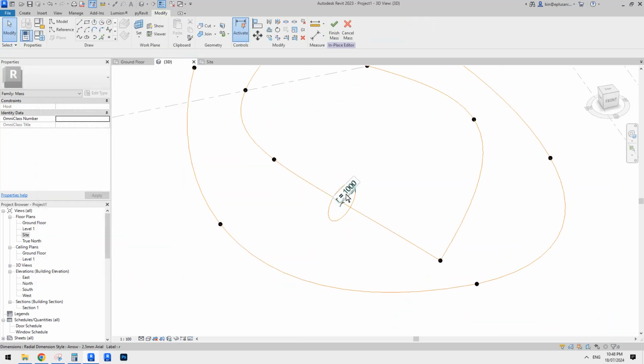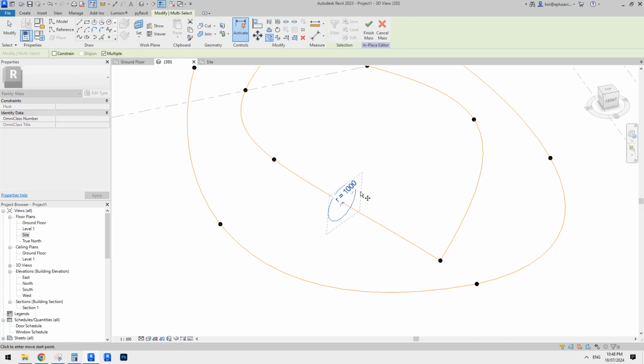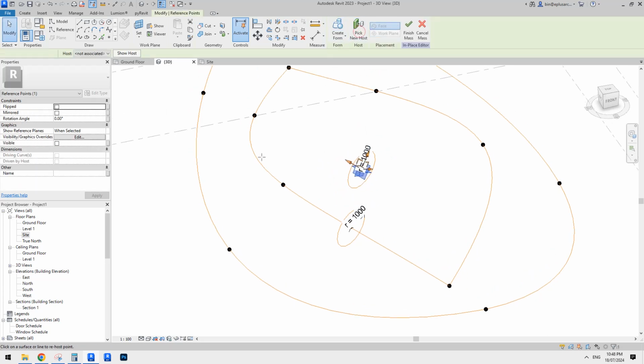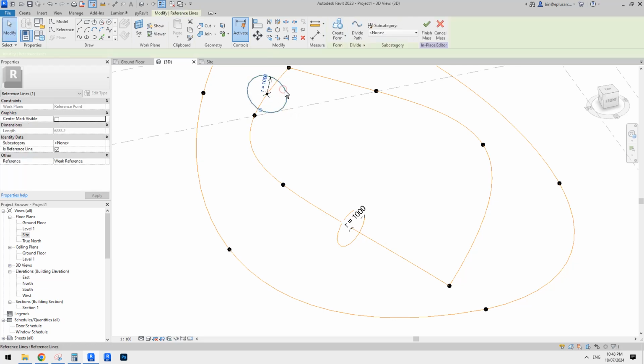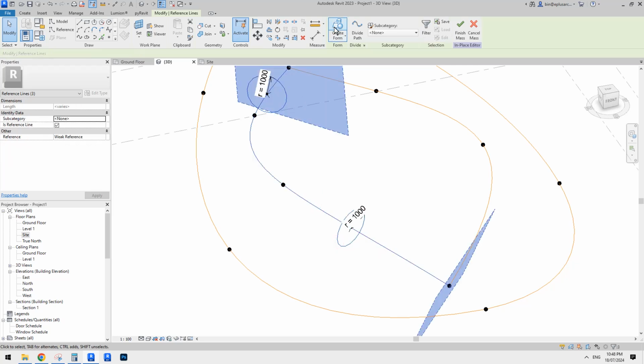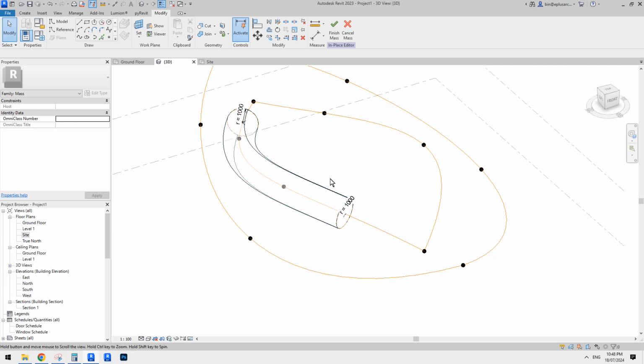And then okay, so that's all we need: the point, the profile, and the parameter, the dimension or the parameter. So let's select all of them, CC, copy, and select the point and pick new host, and I'll just place it roughly here. And then we can select this profile and select this profile and select this path and create a form. Okay, so now you can see it's a very, very big profile, right?